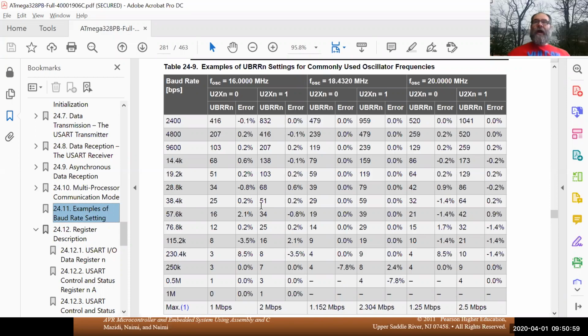It depends on how long you're going to stream without going to idle. So if there's 0.2% error, and I can't do this off the top of my head, but if you were to stream 1 million characters, one right after the other, so you've got one stop bit, and then a start bit, and then a character, stop bit, start bit, and another character, rather than testing the high or the low in the middle of each bit, it's going to begin to drift a little bit.